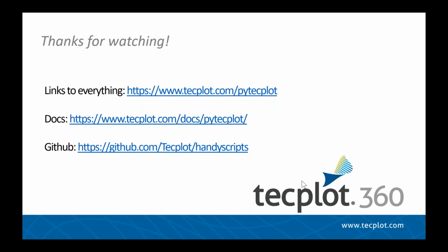If for some reason you need to be using an older version of Tecplot 360, because we do rely on the installed version of Tecplot 360, you need to make sure that your path environment variables are set properly. On Linux, that would be LD_LIBRARY_PATH. On Mac, that would be DYLD_LIBRARY_PATH. And on Windows, that would be the PATH environment variable. All of that's in the documentation.